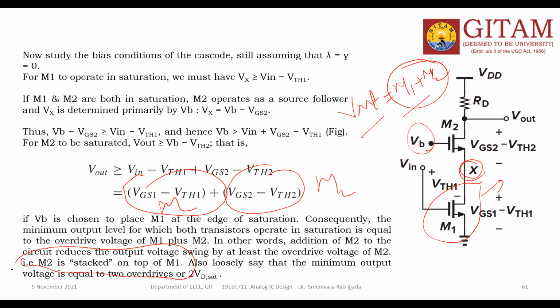Generally, there are many techniques to reduce power in a circuit, whatever the circuit. There are many low power techniques, but one of them is the stacking approach. What is the meaning of the stacking approach? If you see the two devices M1 and M2, both are, of course, NFETs.